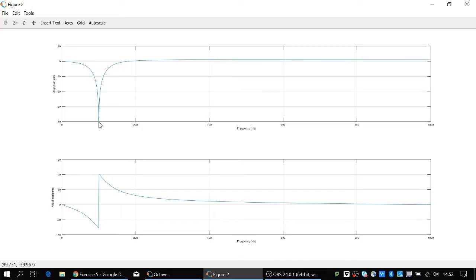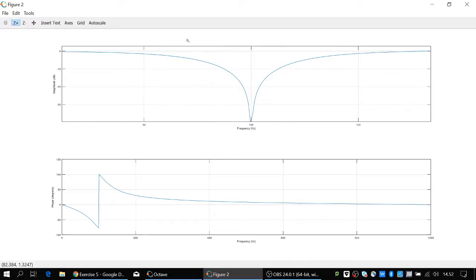That's why it's a little bit short here. But anyways, you can also see, let's expand that part. My design parameter for the 3 dB point was the half width of 40 Hertz. Yep, it's about from here to there. It's about 40 Hertz. Yes, it looks like it works.